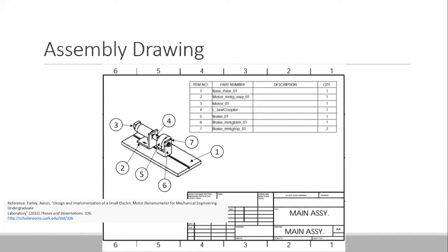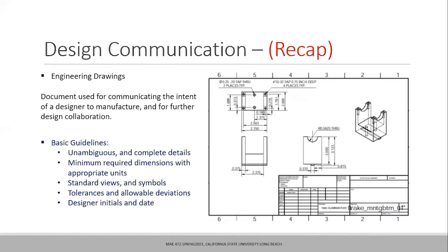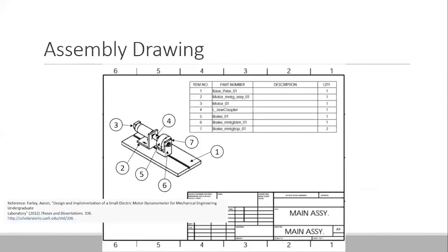And the individual component drawings, the purpose of that is that if I go back to the slide, the purpose of these individual component drawings is that they must have all the dimensions, all the datums, all the references, all the tolerances that are required to fabricate it individually. So there are two different purposes of these drawings. Individual component level drawings should be made for the purpose of fabrication, and sub-assembly drawings and assembly drawings have to be prepared for the purpose of assembly and disassembly operations.